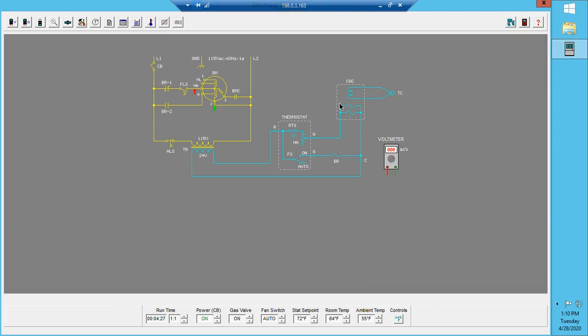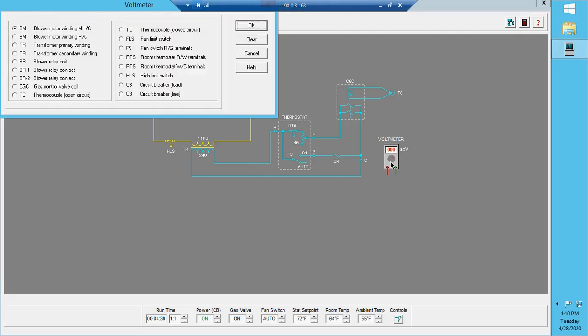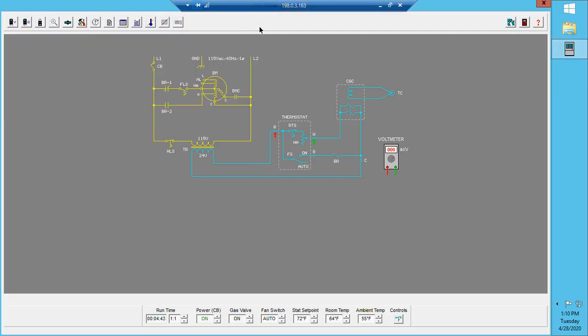So what is happening here? Well, I've got my thermostat. 24 volts powers up my R through my thermostat. Is my thermostat closed? Well, let's see. Let's go to R and W. Okay, thermostat is closed, right? Reading 0 across a closed switch. So why is it not energizing?